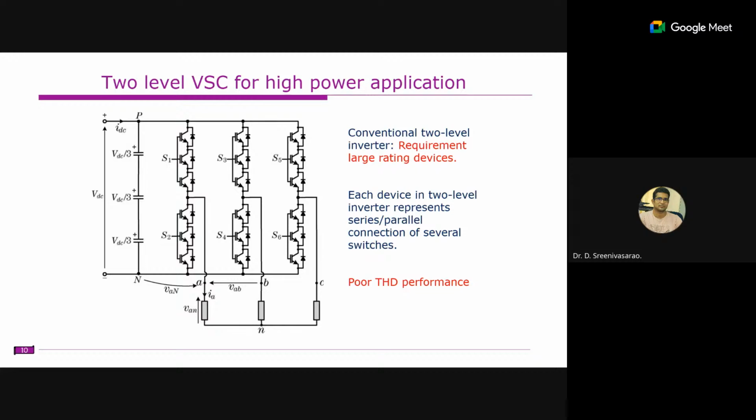The drawback with this one is that the number of switching devices is more, but from the performance point of view, it's still like a two-level inverter. Obviously, if you're designing a filter like an LC filter for a huge voltage like 11 kV, the size of the inductors, capacitors, and their isolation will be much bigger. It also increases cost, size, and weight. So these are the drawbacks.